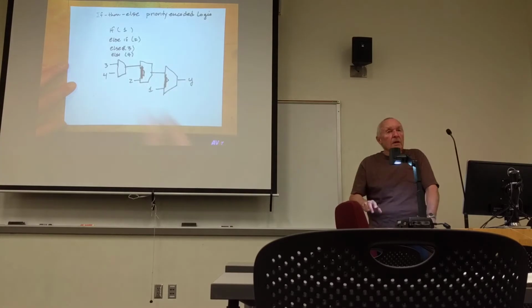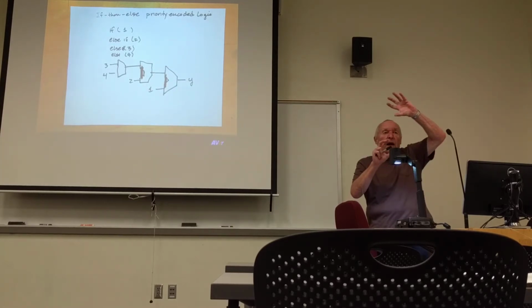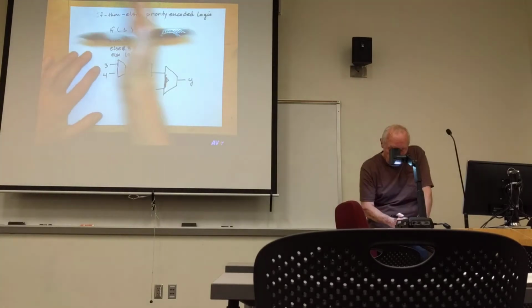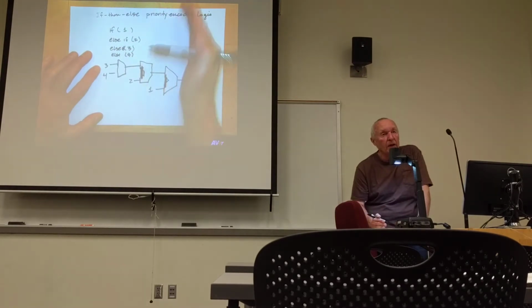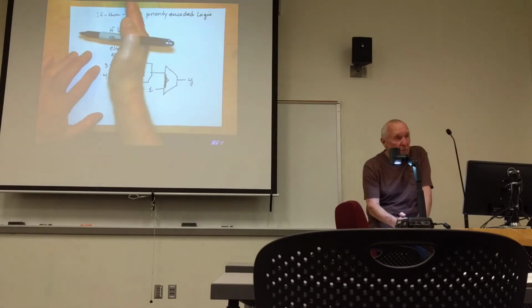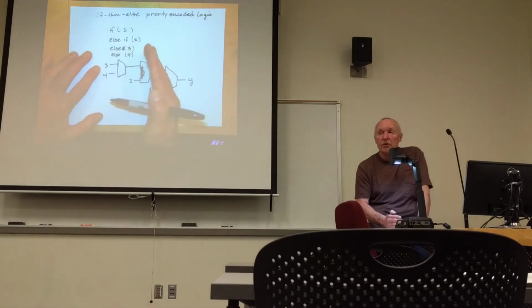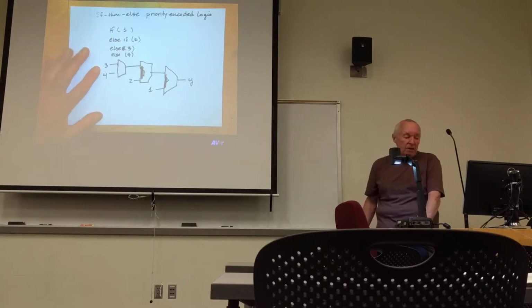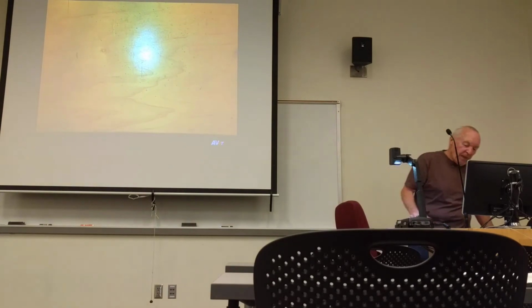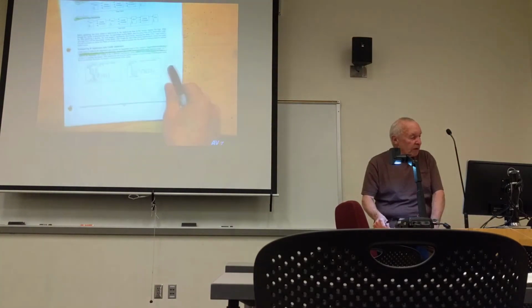The case statement tends to balance this out, where instead of different layers of individual muxes, you have multiple muxes per layer. You have fewer layers, lower propagation delay with casing. That said, here's what they recommend.